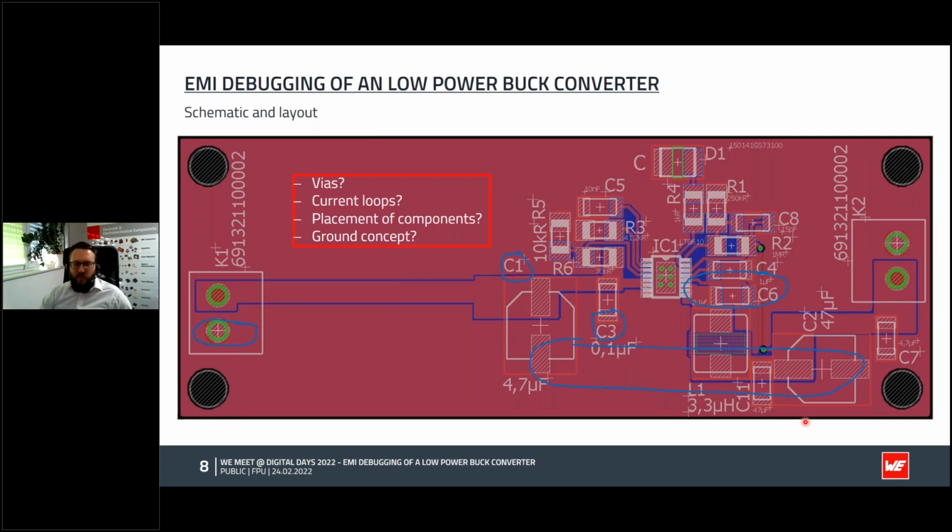And imagine we place a filter component. I will talk about this later, but the ground should go over the filter and not connect directly from the input pin here, because otherwise it would lead to galvanic coupling, and then of course there will be some issues. And again, the overall wires are not really there.